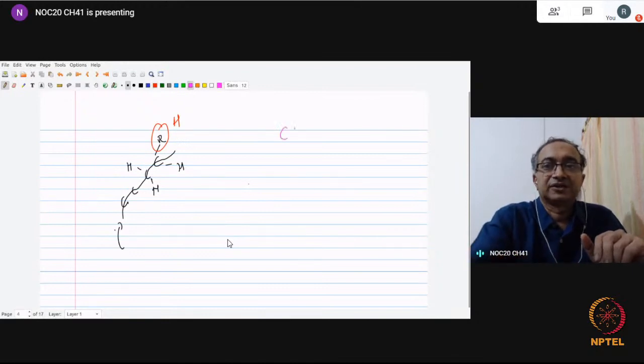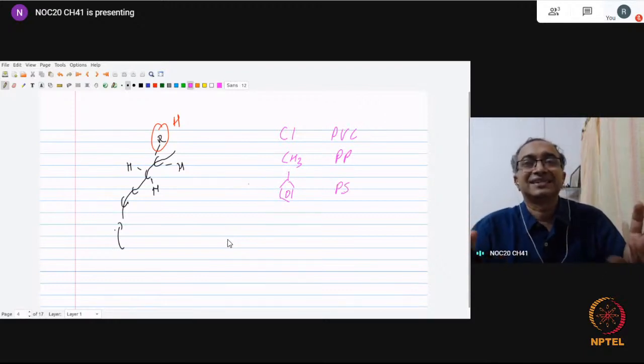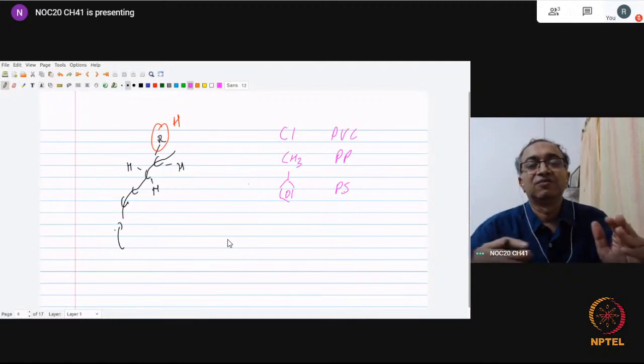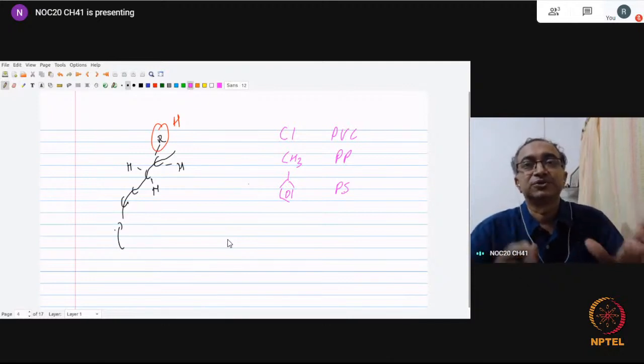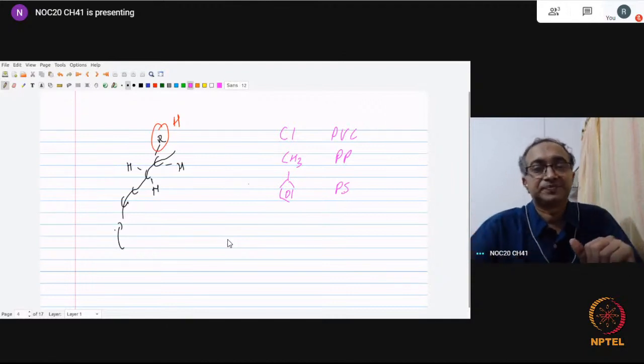You can have either chlorine for PVC, or CH3 for polypropylene, or the benzyl group for polystyrene. In all of these cases, tacticity is possible because you are looking at the location of this group when I am traveling along the polymer chain.